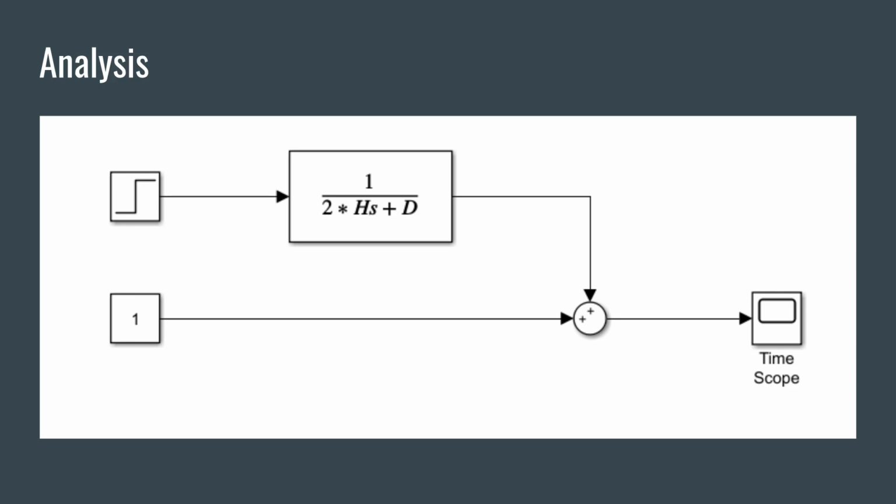Now, the reason we can use step functions is that our system will almost exclusively receive step inputs from load powers. Every device that is added to or removed from the power grid will be a disturbance to the system, and most of these devices that come online will always have instantaneous power requirements that go from 0 when the device is off to their max power consumption in a small amount of time. These disturbances can therefore be modeled as step inputs to the system.